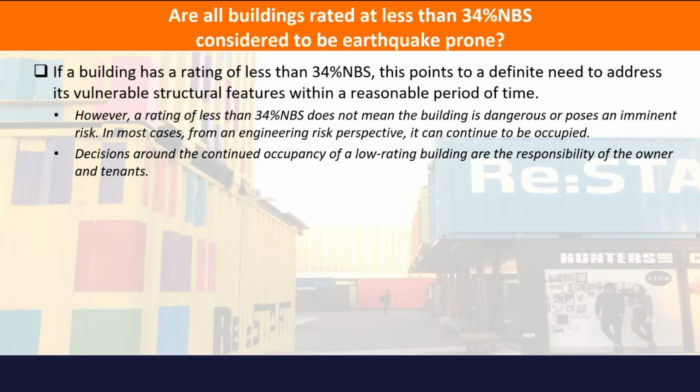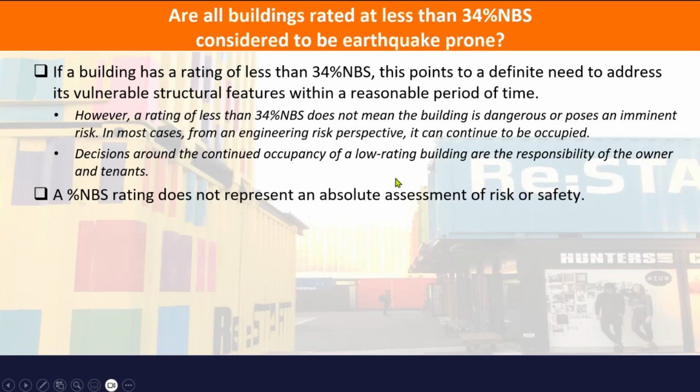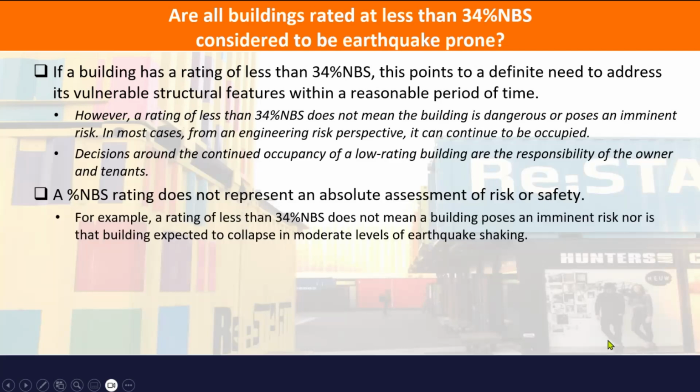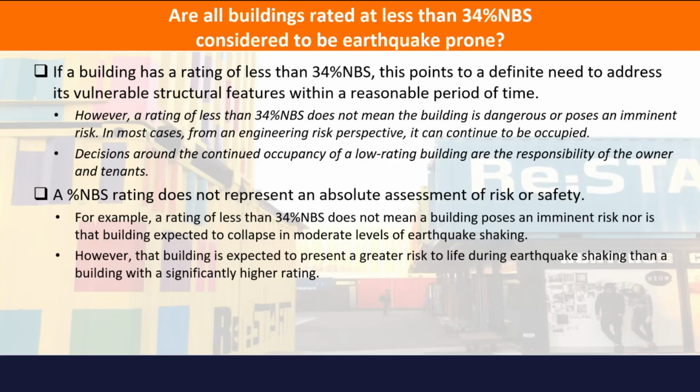Decisions about the continued occupancy of a low-rated building are the responsibility of the owner and the tenants. However, the owner will rely on you as the engineer to inform them. They need to make an informed decision as to how risky it is. It's not an absolute assessment. It's pretty quick and dirty to get a rough idea of the risk. It doesn't mean it's posing an imminent risk or that it's going to collapse. However, it does pose a higher risk than normal during an earthquake.